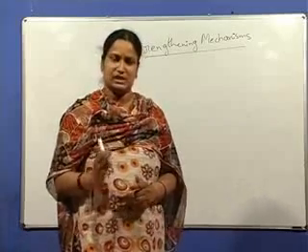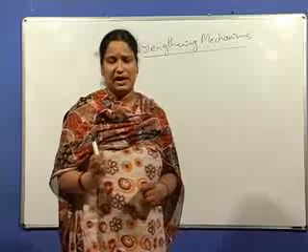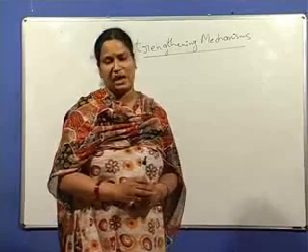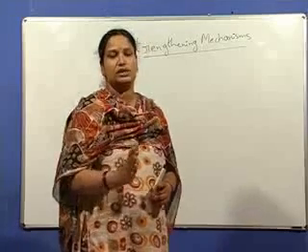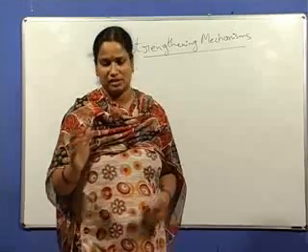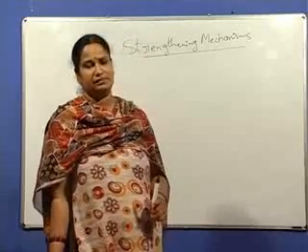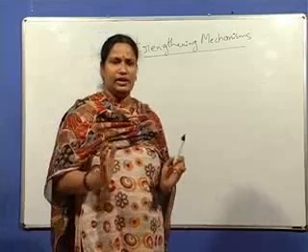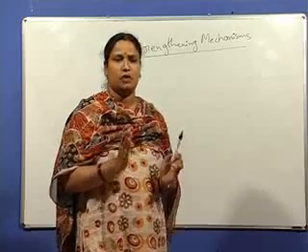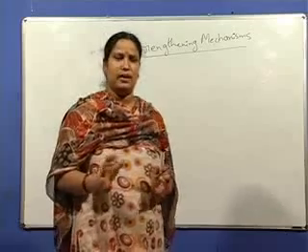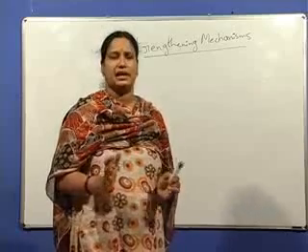What is the main reason for plastic deformation? Movement of dislocations is the main mechanism for slip to take place. That is the mechanism of plastic deformation. So any hindrance or obstacle to the dislocation motion gives rise to strengthening. For an alloy designer or material designer, an alloy can be made stronger by creating obstacles or hindrance to the dislocation motion.